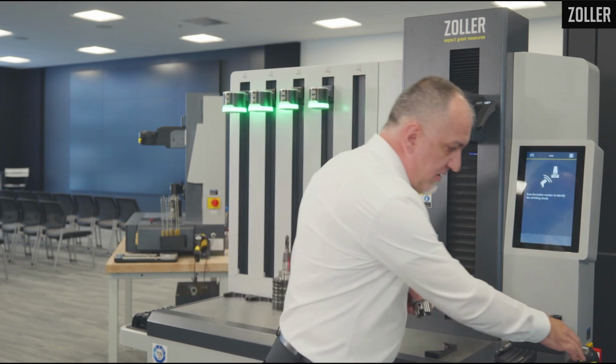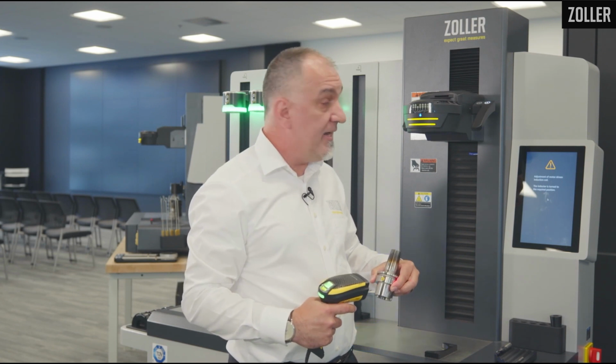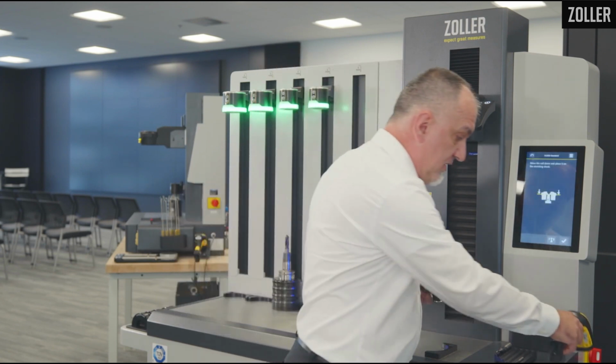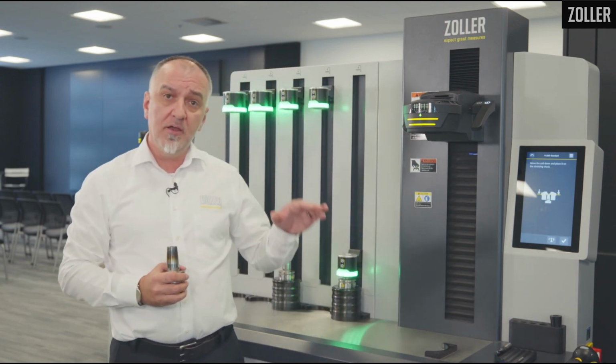What it means, like you saw in this case, this is another holder. In this one here, you see that it goes to a different dimension, a different diameter. This means that from the powerShrink, it goes to the presetter. There you have another scanner, and it just populates the data, the offsets. From the presetter, it goes to the balancer where you balance the tool, and then you have another system at the machines where you scan it, and then you just transfer the offset into the machine.